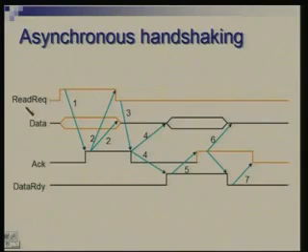So it is a control signal which I am calling read request. When this signal is activated, the meaning of this, which is understood by the memory, is that something has to be read. Memory has to do a read operation and send out data. The data bus, while this signal is active, is carrying the address. So it has to be understood by both the parties that at this time what the data bus is carrying is actually the address. The processor which is sending the address and the memory which is receiving the address should understand what it means.